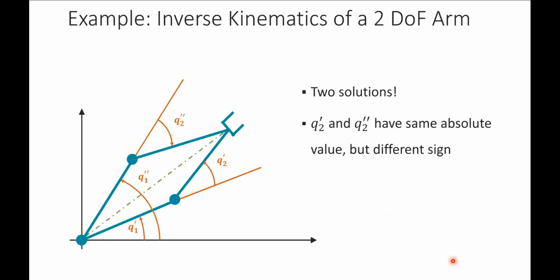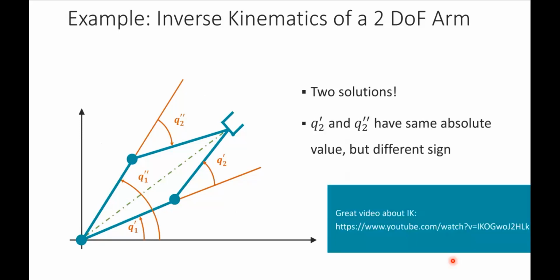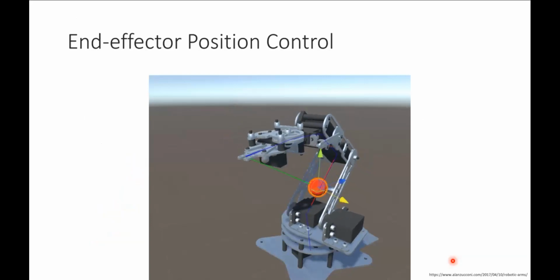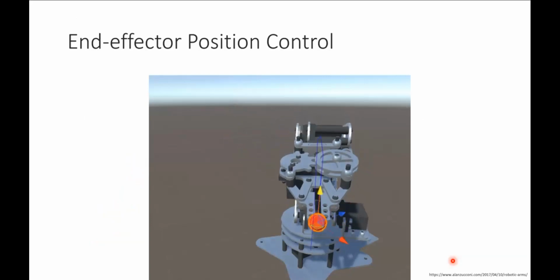So for manipulator arms, we can end up with redundant solutions. And redundancy is something we've talked about a little bit at this point. So when we work out the actual equations, you're going to find that you have multiple solutions, and that's fine. That's something that's good for us, right? Because it gives us more opportunities to get to a valid configuration. But it also means that it's a little bit harder for us to arrive at those solutions, right? Because now we're not necessarily going to have X equations, X unknowns, and it's not always going to be solvable all the time.